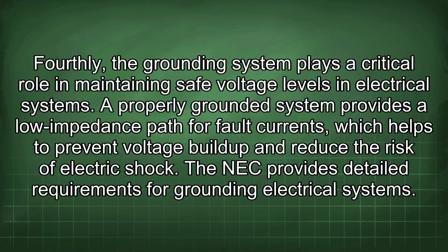Fourthly, the grounding system plays a critical role in maintaining safe voltage levels in electrical systems. A properly grounded system provides a low impedance path for fault currents, which helps to prevent voltage buildup and reduce the risk of electric shock. The NEC provides detailed requirements for grounding electrical systems.